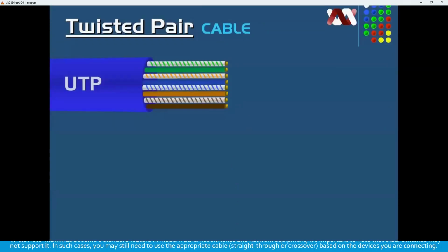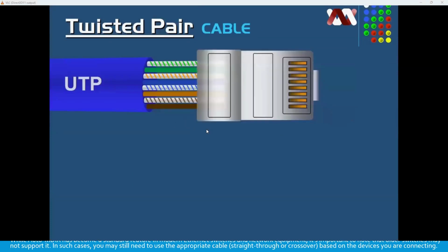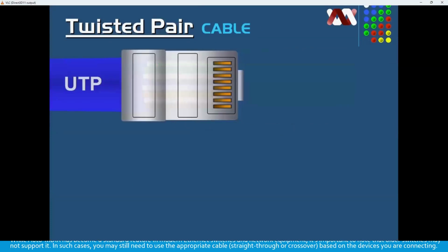So this is a cable, right? And that's your connector. Make sure your connector is plugged almost to the end of this cable, and make sure this jacket is inserted in. This jacket stays at least from here until here. You can go further here as well, but there is less gap here, so it will be very hard. So make sure your jacket must go here. Otherwise, you have a problem. It can come out.